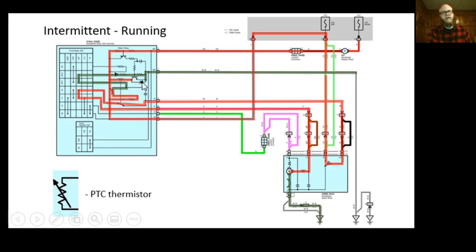You can see the diode and the Zener diode here, how they're working, and then the fact that this transistor and this PTC thermistor, which is also semiconductor, as the temperature increases, the resistance increases really, really rapidly. We're seeing as we're adding all of these bits of information together, now all of a sudden I understand how this circuit works.